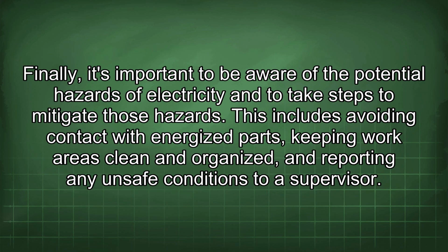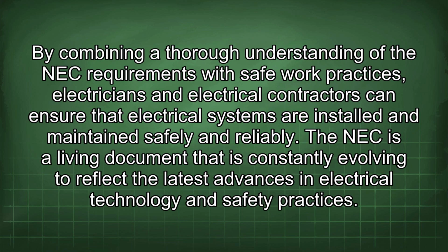Finally, it's important to be aware of the potential hazards of electricity and to take steps to mitigate those hazards. This includes avoiding contact with energized parts, keeping work areas clean and organized, and reporting any unsafe conditions to a supervisor. By combining a thorough understanding of the NEC requirements with safe work practices, electricians and electrical contractors can ensure that electrical systems are installed and maintained safely and reliably.